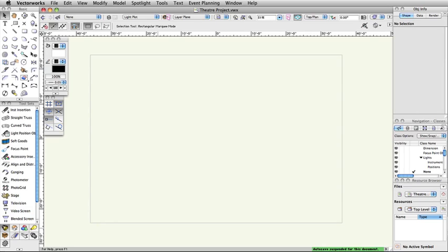We will now create a couple of lines to represent the center line and plaster line, as well as place a locus point which will be used as a reference for the start of the theater walls. Then we will turn these objects into guides. In the view bar, set the active layer to Theater Architecture. Double-click the Line tool in the basic palette.